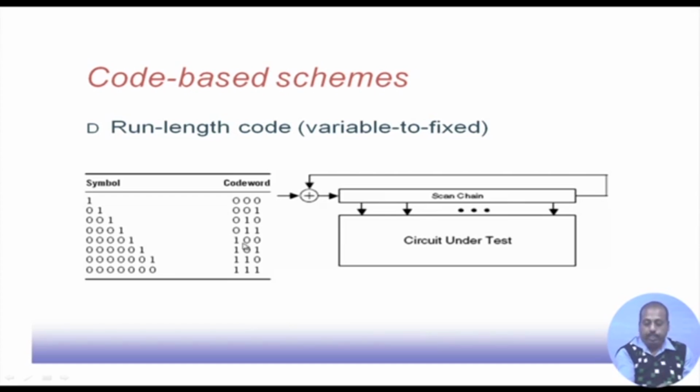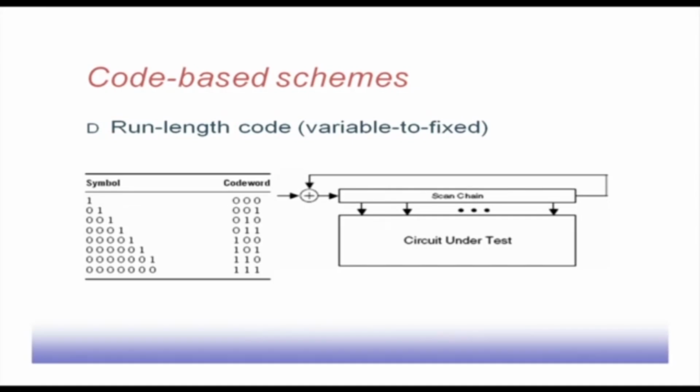At the decompressor end, we can recompute the test pattern given the code word information. In the ATE we are storing the code words, and instead of storing large runs of zeros, we are storing the corresponding codes only. That code is getting transferred to the decoder, and the decoder is in turn computing back the original symbol.